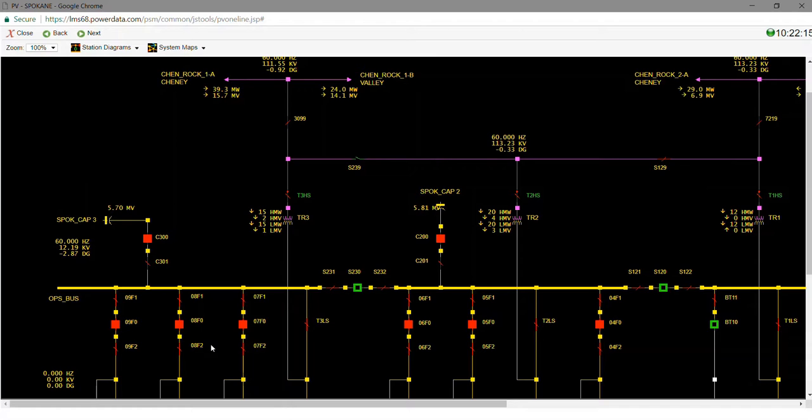They are manually operated by substation personnel, and they have to have a very specific set of conditions in order to be operated. Either both sides of the switch have to be de-energized in order to operate it, or you are maybe just energizing a small section of bus. So the things they cannot do: they cannot energize transformers, they cannot energize lines or loads or anything like that. Anything greater than the circuit breaker itself or a small piece of bus work is more than that can handle.